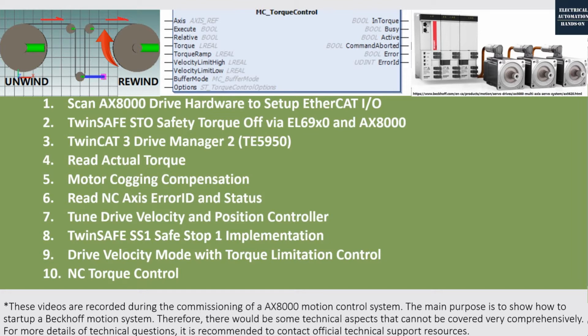It's still fine, but if we use velocity control, the rewind diameter needs to be measured accurately. In some cases the diameter cannot be measured accurately, for example if the web material is transparent, the laser sensor cannot measure the transparent material accurately, or in some cases the tension sensor is not available. In those cases, torque control may be a proper way to control the rewind.